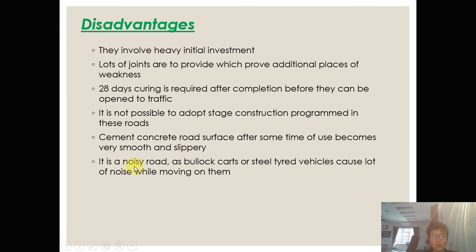And the most common disadvantage of concrete pavement is the noise. You have come across stretches of these concrete segments on our highways. They're very, very noisy. Extremely noisy. So this is where flexible pavement absorbs some of the friction and some of the noise. That's why it takes away the annoyance of the buzzing sound. But with concrete pavement, you do not have that. You just have to bear with it.